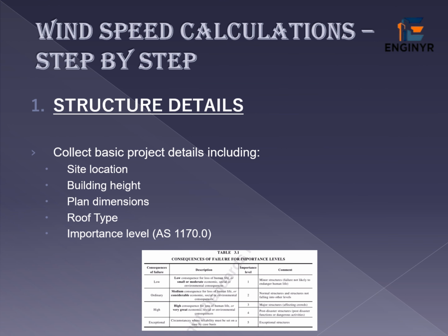The first step is collecting the basic structure details, including the site location, building height, plan dimensions, roof type, and importance level. These parameters form the foundation for accurate wind speed and wind load calculations.